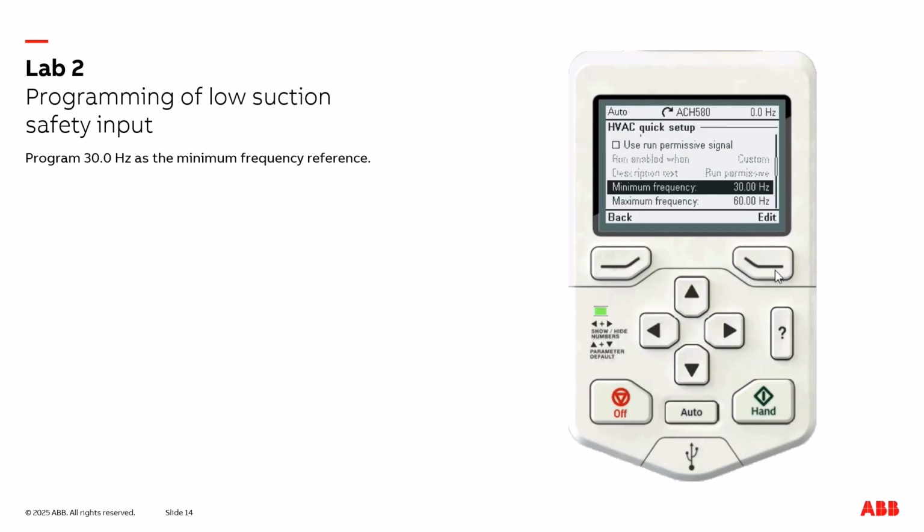And the important thing is this minimum 30 hertz is applied to the drive in both auto and in hand mode. Basically, any way the drive runs, any type of run source, the drive will always run at a minimum of 30 hertz.